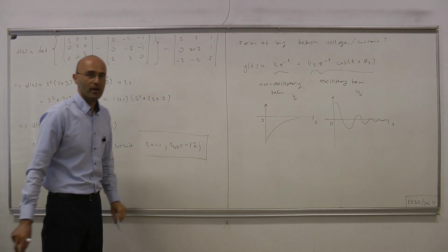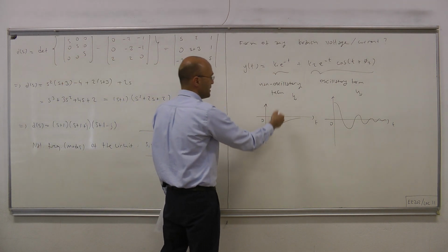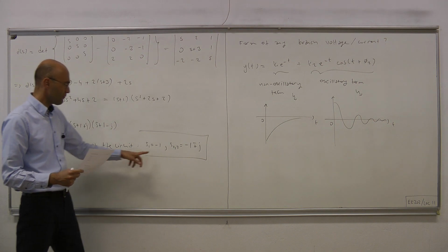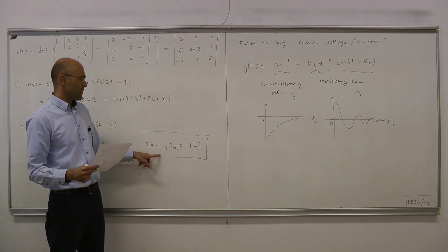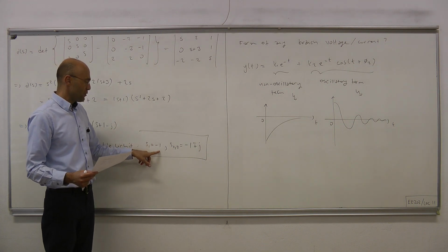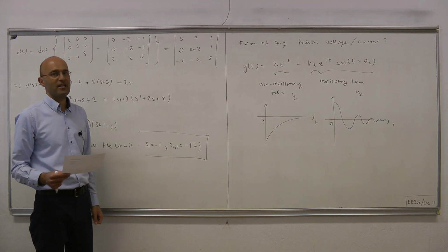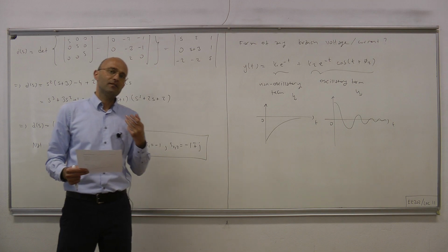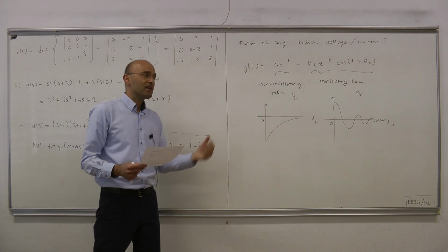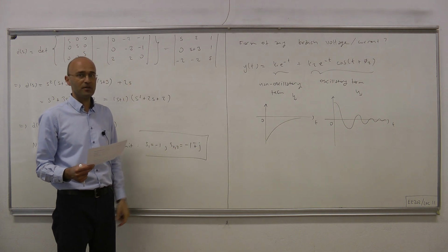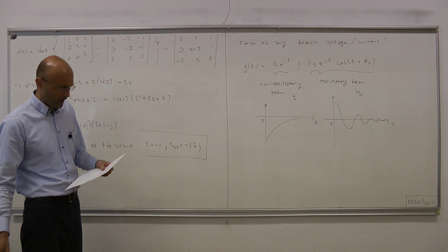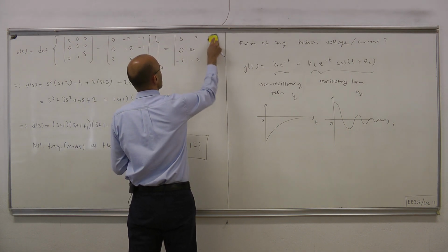So that means, mathematically speaking, we have to excite the mode that corresponds to the natural frequency at -1. All we have to do therefore is, since we have the A matrix, figure out the eigenvector corresponding to the eigenvalue at -1, and then pick the initial conditions so that x0, the initial state vector, becomes that eigenvector corresponding to the eigenvalue at -1. So therefore let's begin our part B.